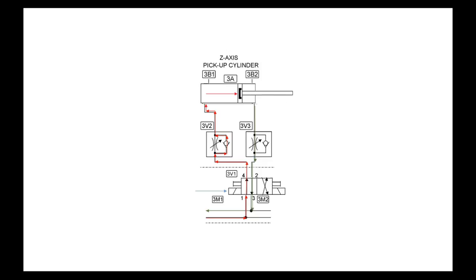On the other side of the flow control, it would be extremely low. What you've got to imagine on these fluid valves, and this is true on hydraulics too, is that they'll draw the symbol in its at-rest position, right? You understand? And you've got to visualize it shifting. Notice the ports don't move. By the way, you notice the way they number these, the odd numbers are on the source side, and the even numbers are on the load side.